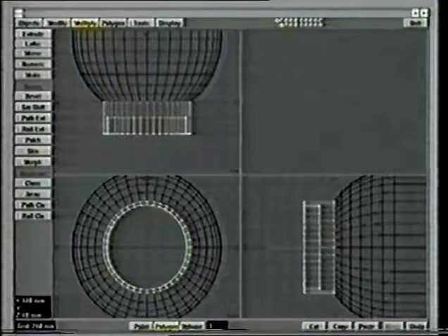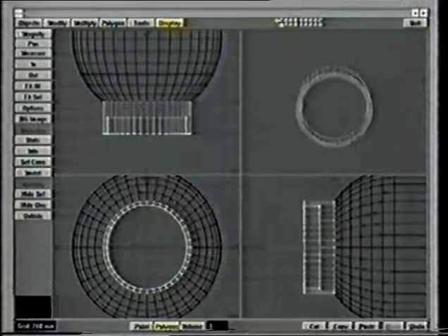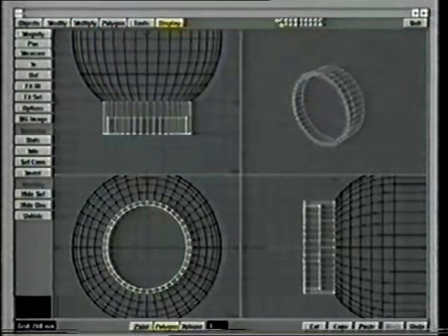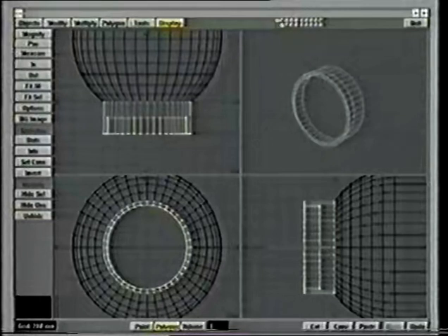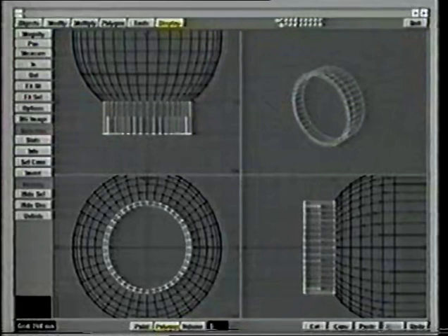And there it is. Let me just pull up a front face display, and you can see there's the lip all around the edge and then there's the recess inside. And it's just a sort of demonstration as to how useful the bevel tool can be, because when you're trying to make accurate extrusions of shapes, I find it actually more useful than using extrude itself, because it always works in the direction of the surface normal.